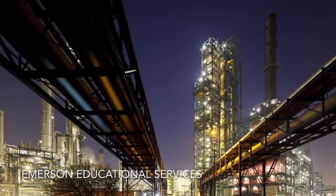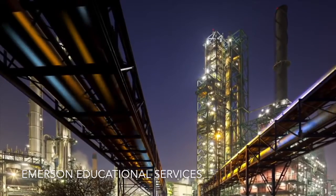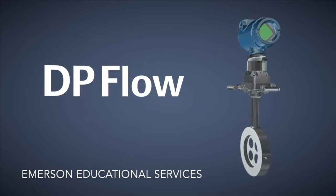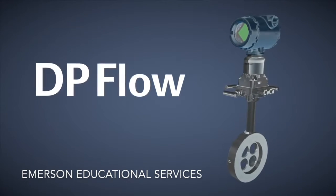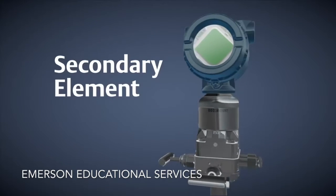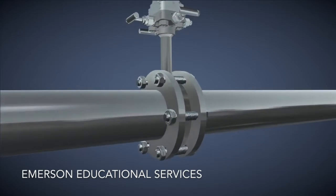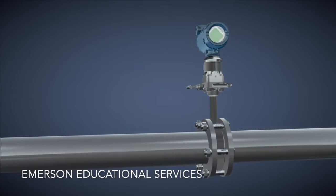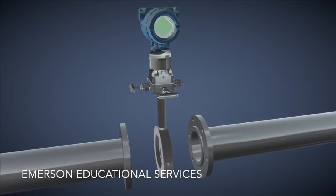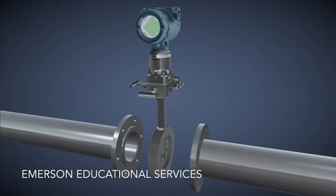Flow measurements are essential to running a plant efficiently and safely. There is an array of flow measurement technologies available, including differential pressure flow, also known as DP flow, which utilizes a variety of measurement instruments. DP flow is measured with a combination of a primary element and a secondary element. A primary element is placed in the pipe to create a differential pressure while connecting the secondary element to the process. The secondary element, or transmitter, takes measurements from the primary element and converts them into useful quantitative values and transmits those values to a control system.